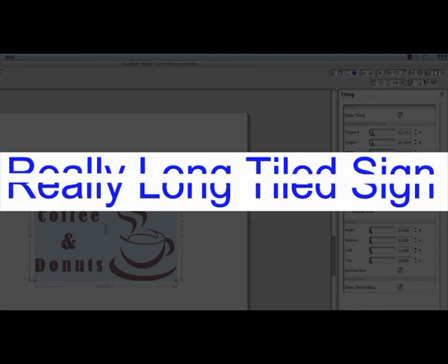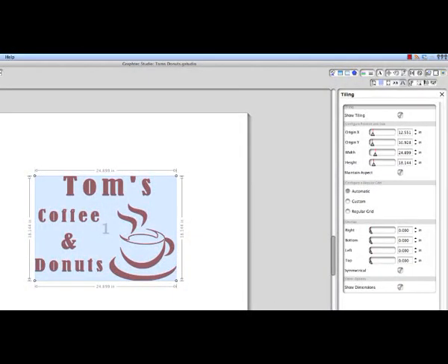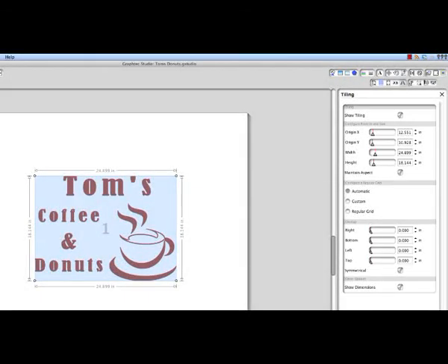When a design is tiled, each tile will be sent separately. In other words, each tile will be cut individually. Here, the job design shows that there is only one tile assigned to it. This is because the design size will fit within the cut area of our cutter. The options in the side panel allow you to configure the tile pattern. But first, let's resize this job design so that it is larger than the media page size.